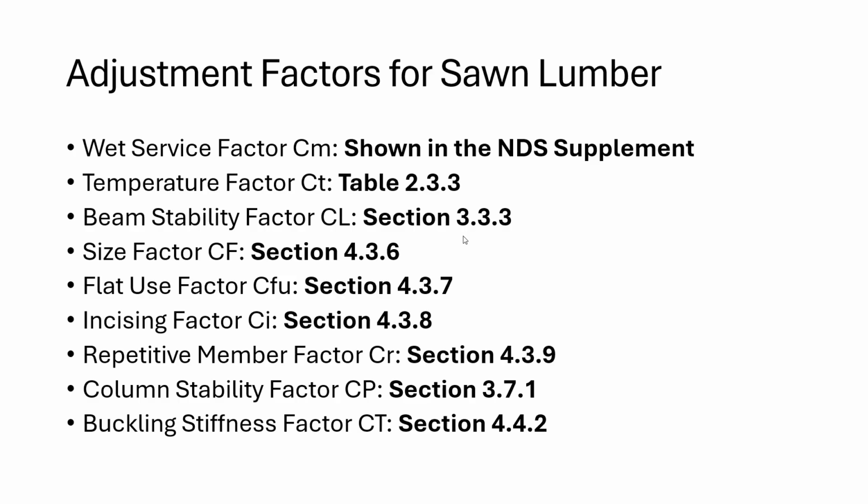Temperature factor, this is in chapter 2, because this does not change across each section. This can get you, I will say, because I'll take an example. If your temperature ranges between 125 and 150 degrees Celsius, for compressive strength, you're going to reduce that number that you pull from the NDS supplement by half.